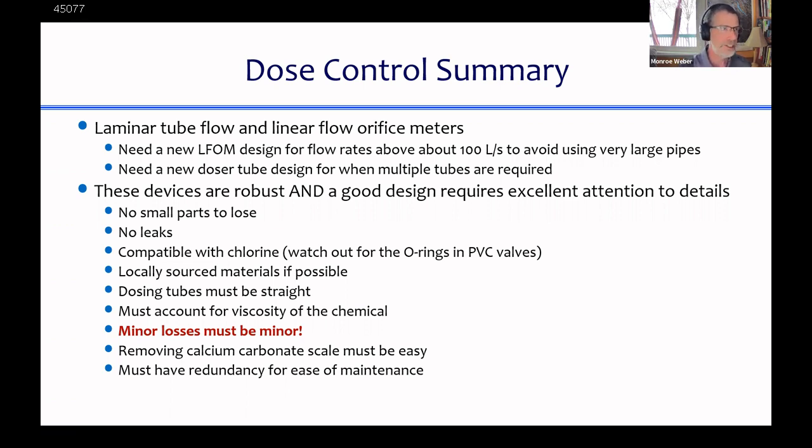And just drilling this home, minor losses have to be minor in this system because minor losses go with the square of the velocity, and we want a linear system. And chlorine is going to deposit calcium carbonate, so that has to be easy to clean.